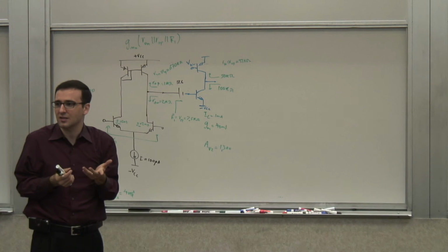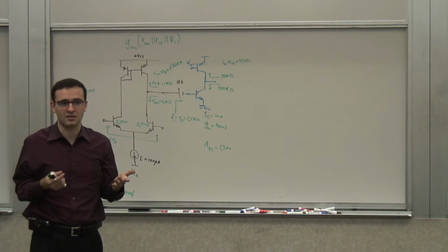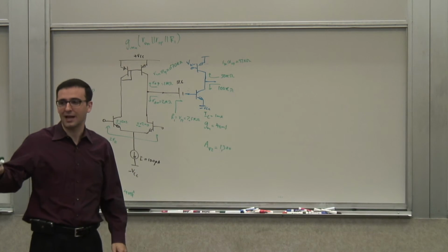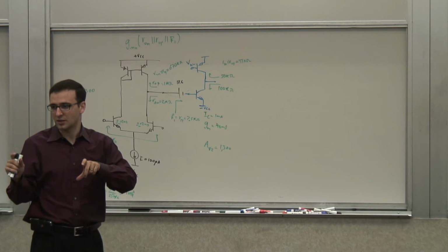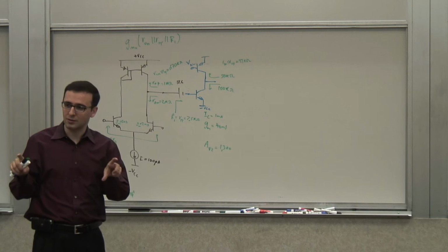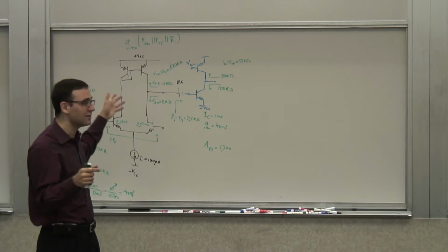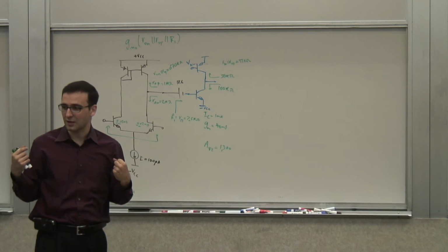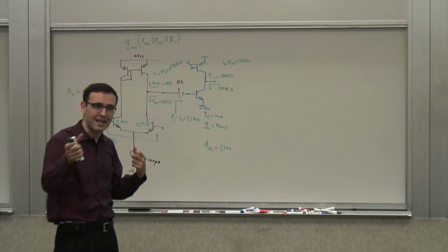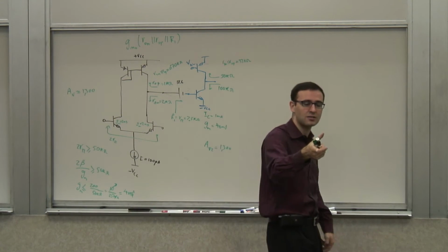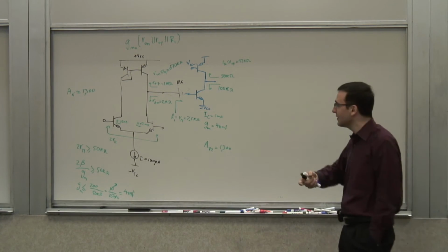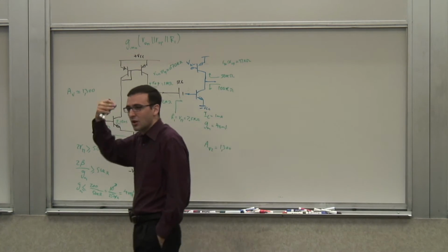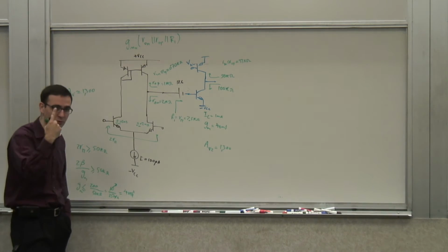It's a bad way of designing things. You can never maintain VCC constant. Even if you're using a battery, the battery in the beginning of its life and the end of its life will demonstrate a different voltage. And even if that were not the case, you may have other things that draw current out of a real battery, and because of its internal resistance, the voltage that the battery presents to you is going to be different at different times, right? So even that's not going to work. I mean, it's not realistic to assume that your supply voltage will be one single value.